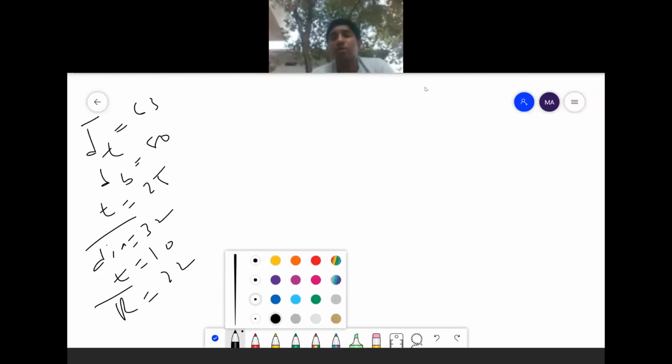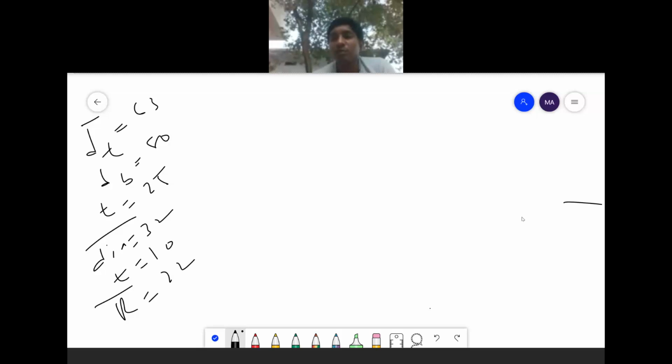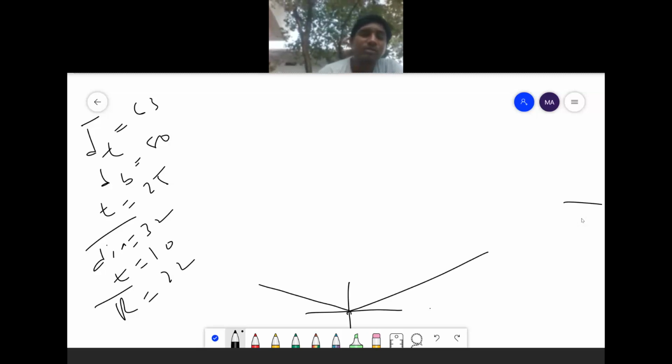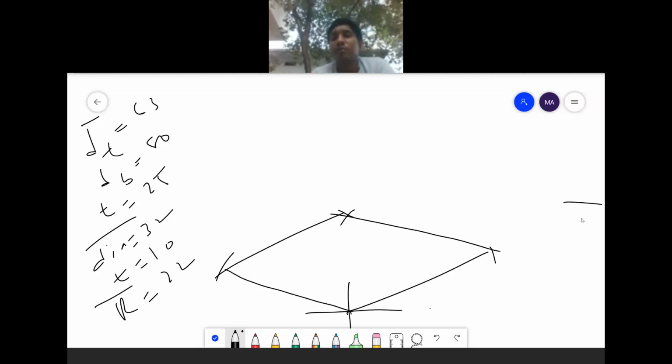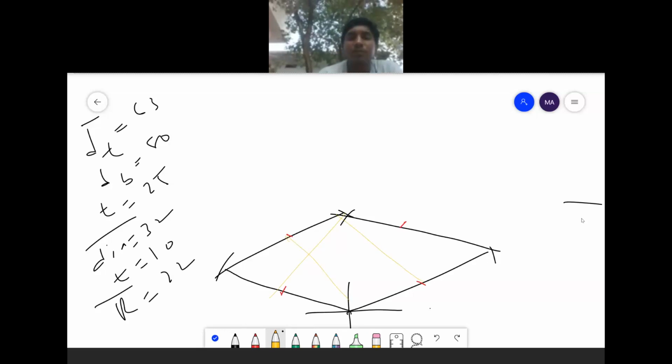So first you will draw the first term of this cone. First I am taking like this. I am drawing angle 30 degrees. I am cutting 80 here, 80 here, from here I am cutting 80, 80, which will form a cone like this. After that I'm marking the midpoints: here one midpoint, here one, here one, here one. I'm using the four center method to construct a circle. You know how to draw using the four center method.